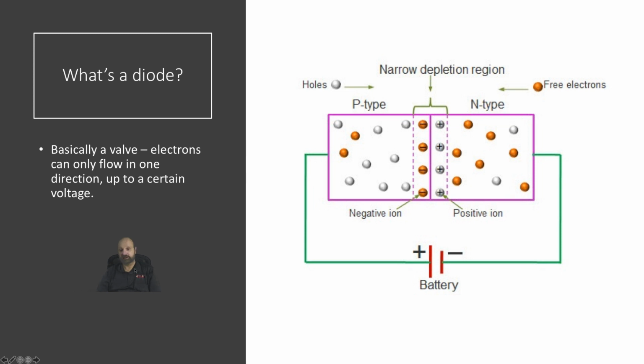Okay, so you can make diodes this way by selectively implanting certain areas, making some areas P, some other areas N. You do this with masking. You do a hard mask, say a silicon dioxide hard mask. So the dopant goes into the silicon dioxide, and it also goes into the crystalline silicon where it's open, right? Remember, the mask is open in some areas. So the parts that are covered, the ions go into the oxide, which is later stripped away.